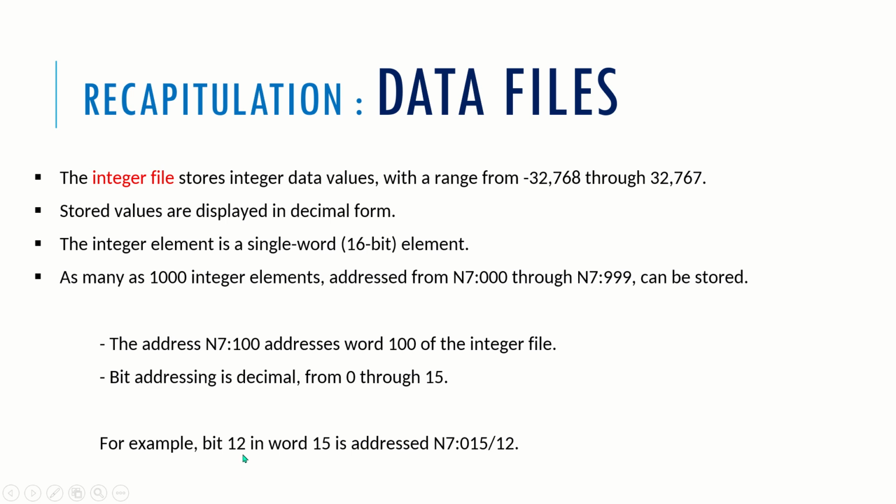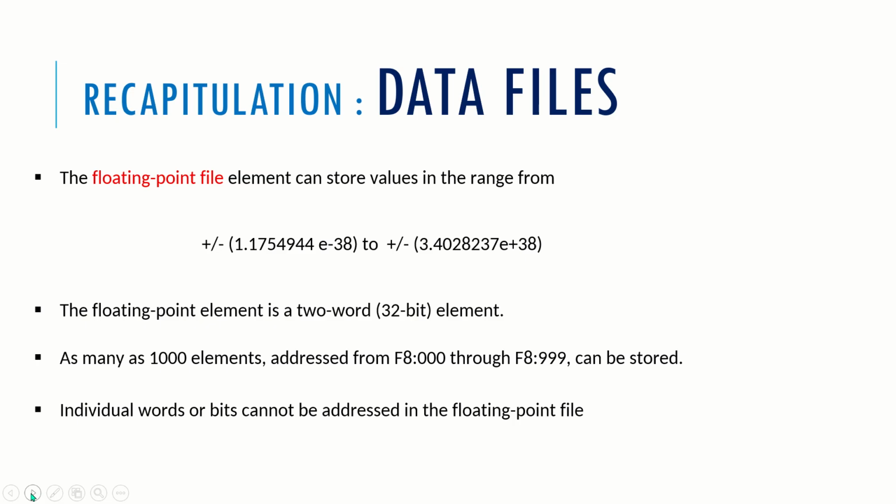So the example is given like this: bit 12 in word 15 is addressed by N7:15/12. That is, this is the word 15 address, in which we are talking about bit 12. Okay, so this is the example that you need to consider.